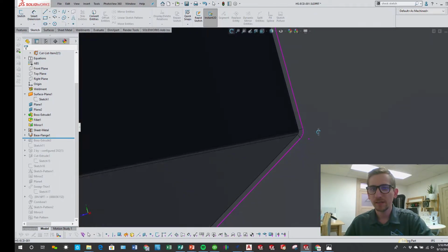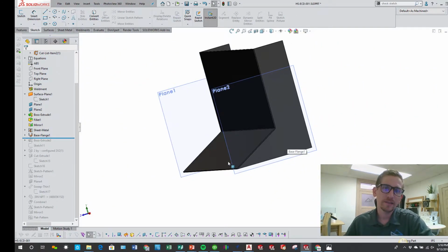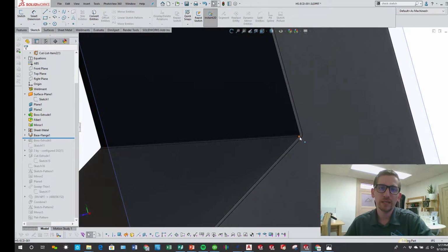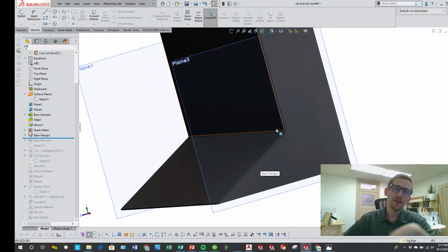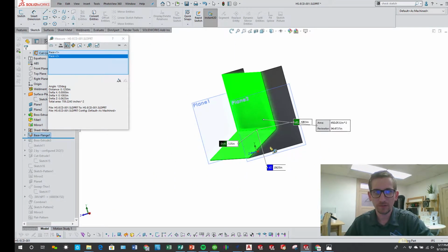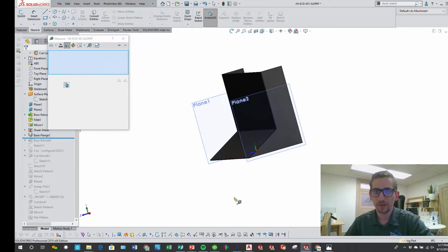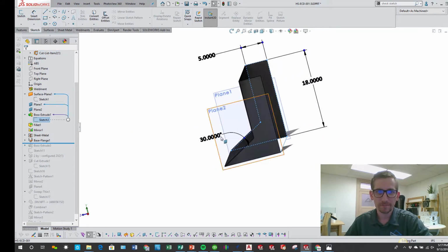And so what I was thinking was that I could utilize the plastic manufacturer to say, hey, take a sheet and I want you to heat up a certain distance in and just bend it. I made it to where this is going to come in at 30 degrees. Well, it says 120 there, but it's a 30-degree angle based off of my existing sketch 3 there.